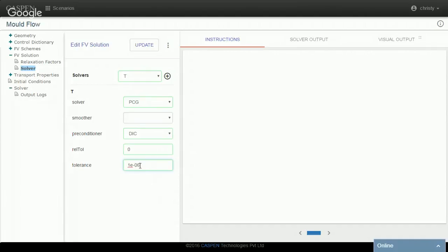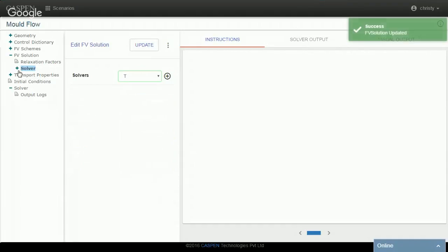So basically, the tolerance is an indication for you to know whether the difference between two iterative residuals is falling within this value or out. If it is falling within, it shows that your solution has converged. If it isn't, that means you may have to increase the time duration, and check if you're achieving convergence, or you may have to change some other parameters to stabilize your convergence criteria. So after this is set, we've just simply put a temperature into the solver.